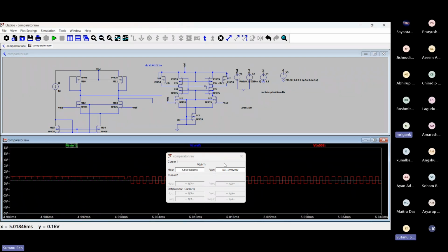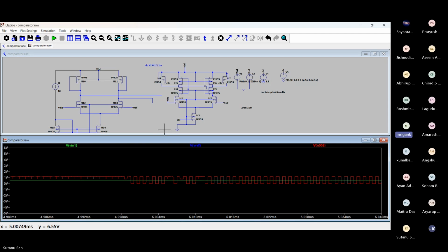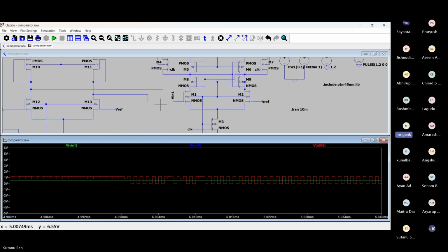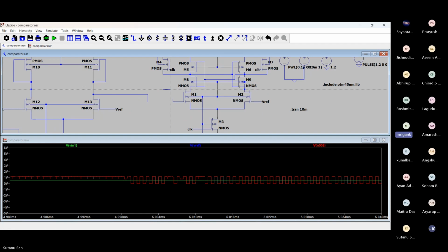After that, all the cycles. Is that clear? Yes, understood. Now the thing is, if you put the preamplifier, maybe this will go slightly better depending upon the gain of the preamplifier. So if the gain is, you know, 10 in this case, how much gain did you design it for? It was designed for actually 10. I'm getting around 19 dB of gain. So with this gain, you can check what is the resolution you are getting.